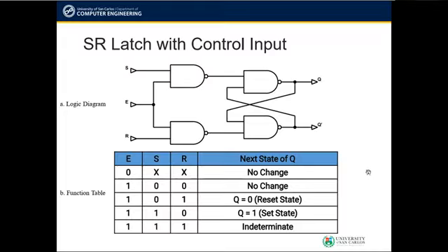Here we have a variation for the circuit implementation of an SR latch. The circuit shown here is an SR latch with control input. The control input is specified by this additional input E. What it does is simply enable or disable the circuit.